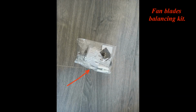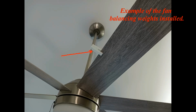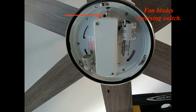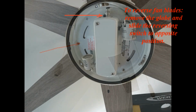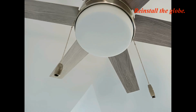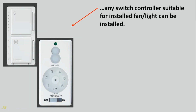Fan blades balancing kit. Attach balancing weights to the fan blades if fan needs to be balanced. Example of the fan balancing weights installed. Fan blades reversing switch. To reverse fan blades, remove the globe and slide the reversing switch to opposite position. Reinstall the globe. In the place of combination type, double, single pole switch, any switch controller suitable for installed fan light can be installed.